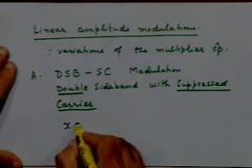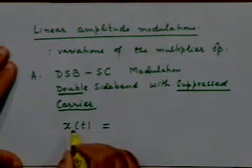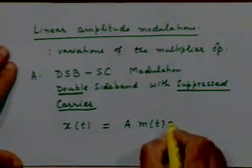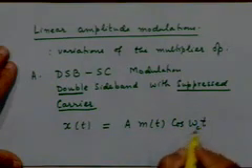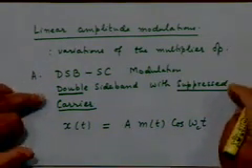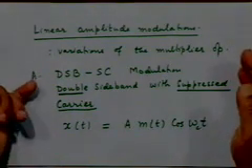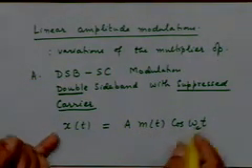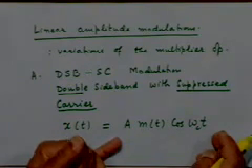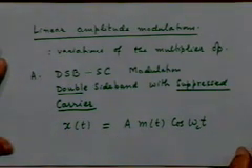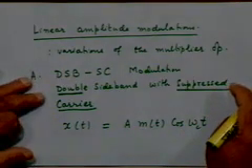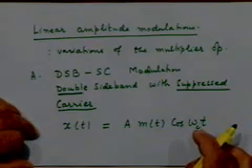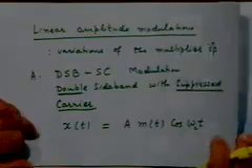The basic signal is the one that we just discussed. The modulated signal x of t is A m of t cosine omega ct. Right? Let's try to see why we call this signal by this name. So when I refer to DSB-SC modulation, we are referring to this signal. Message m of t multiplies the carrier A cosine omega ct. Before we go into the reason for calling it by this name, let's once again review what this signal looked like, physically.